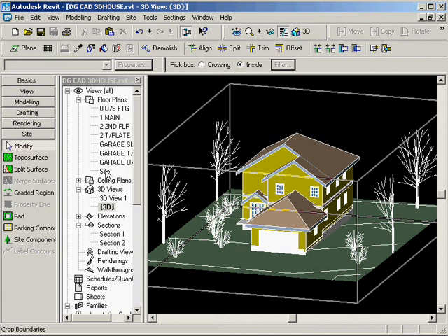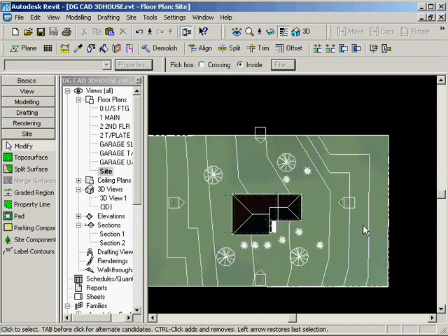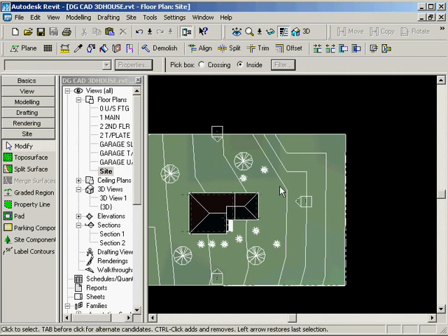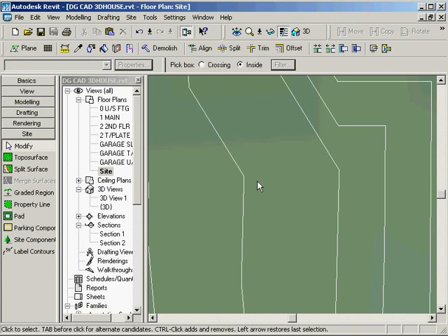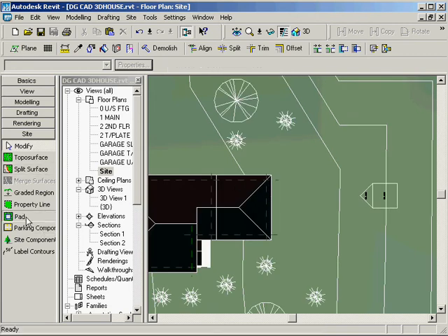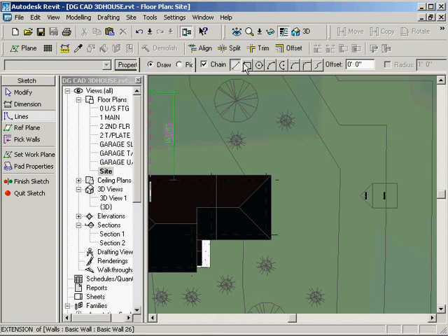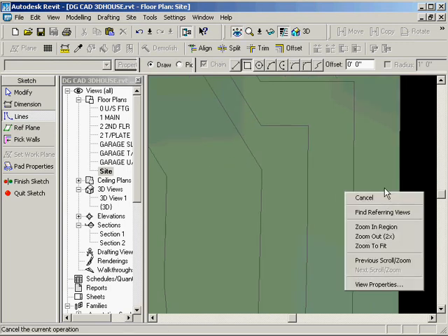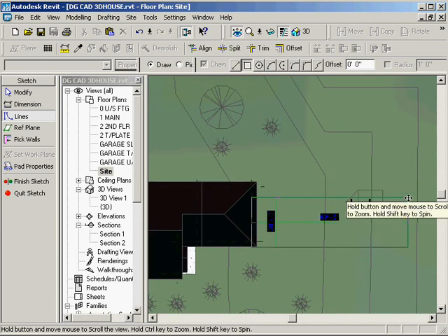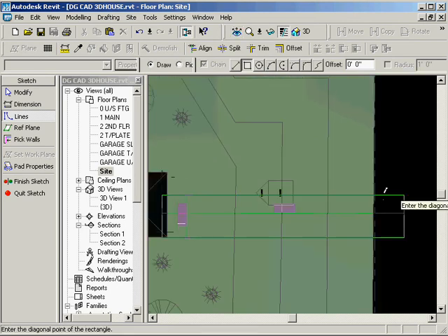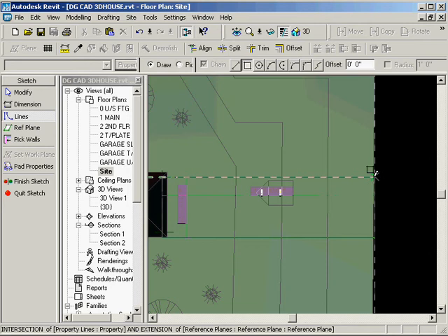And now we'll go back to site plan again. What I'm going to do next is put a pad in here for our driveway, and we'll make that an asphalt material. I can see my green lines. I need to add in a pad, and a pad is just a depression that you place inside of the site. So I'm going to go to here, and do it this way. I'm going to go right to the edge of my property, for instance, out to there.